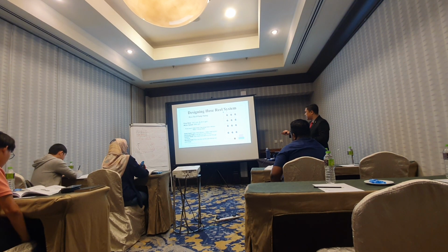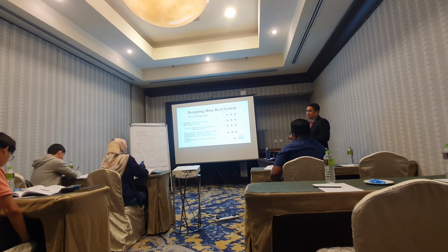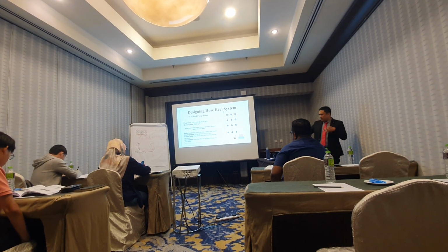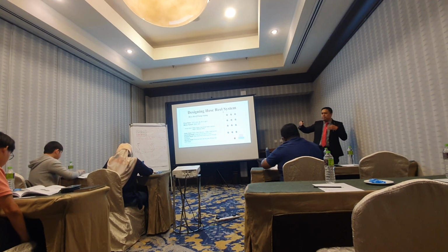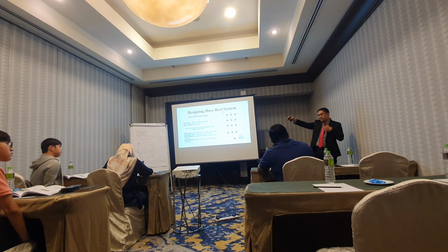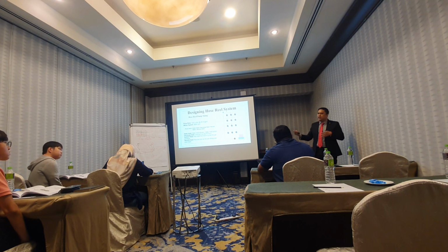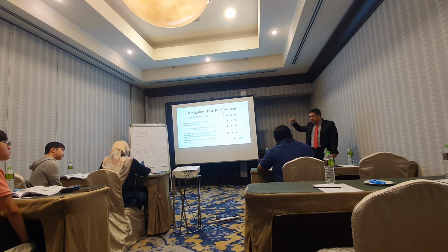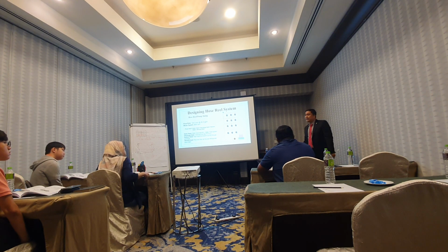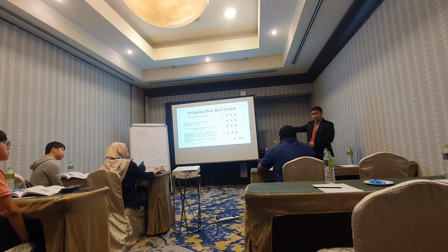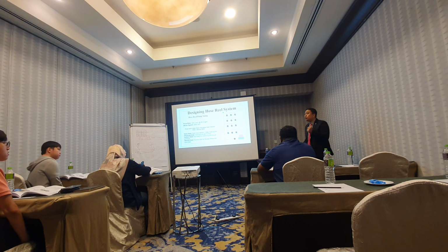Static head is the height of the building itself. It must be more than that. If the building is not very long, meaning the stretch of the building is just about 60 meters, you can add another 20% of the building height, and that will be the head. If it is too long, maybe you can add another 30 to 40%. That is the rule of thumb.